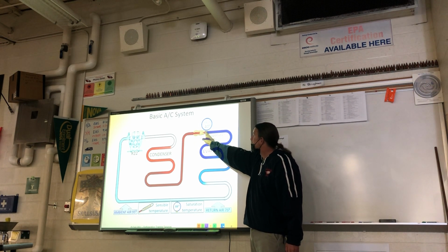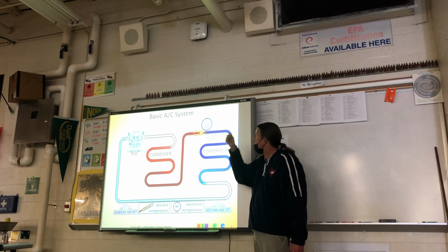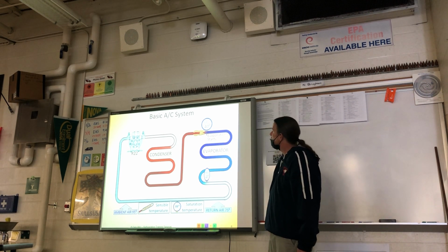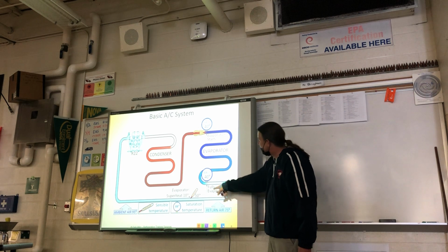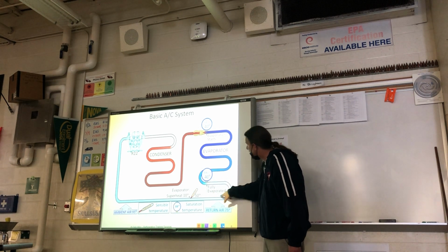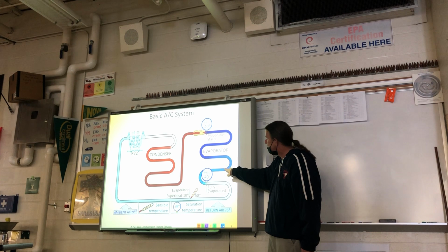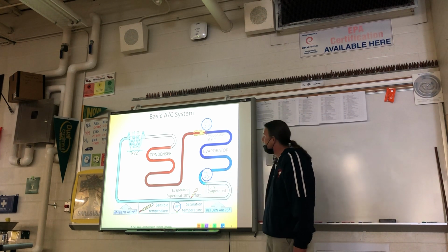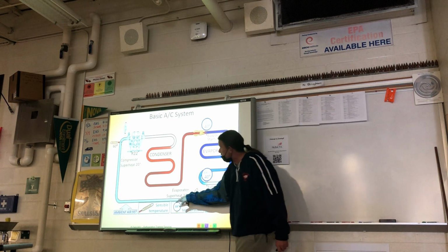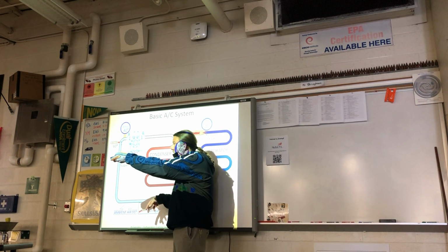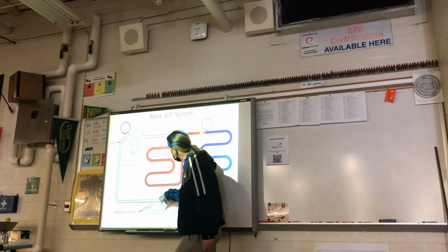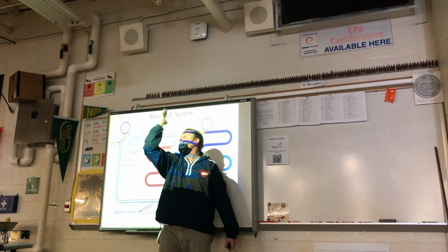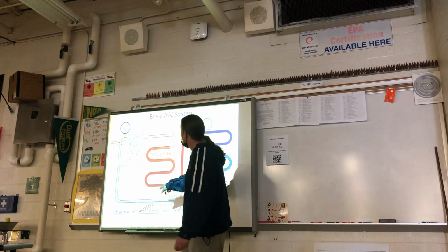So our evaporation comes right when the metering device changes from high to low pressure liquid, and that liquid boils off immediately and starts to flash. And then by the time we get to here, it's fully evaporated. And then that means that if it's 40 degrees here and it runs through one more pass with this 75-degree air blowing over it, I'm going to have 10 degrees of superheat. And by the time, if I got a real long run, like that run over there, it's not that long. But if I had to go to the outdoor unit where it was out back, that's going to be a real long run that we might have it going through this 75-degree room, and it's going to heat up another 10 degrees.